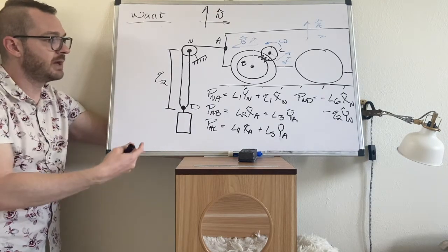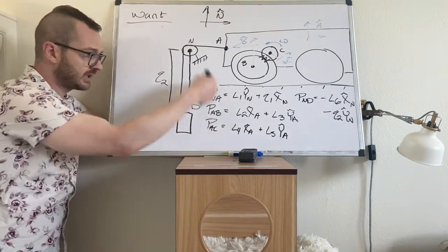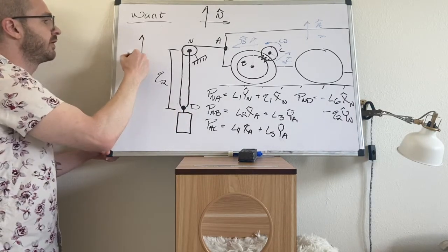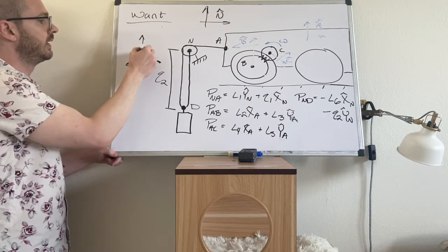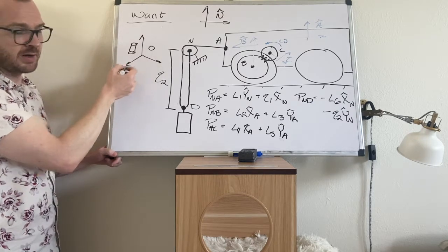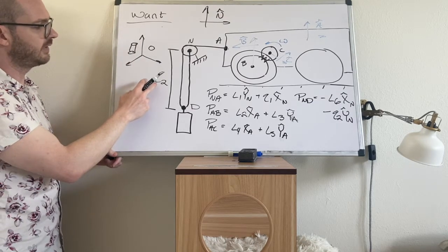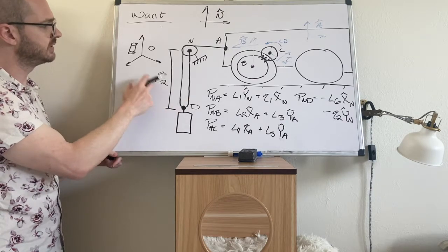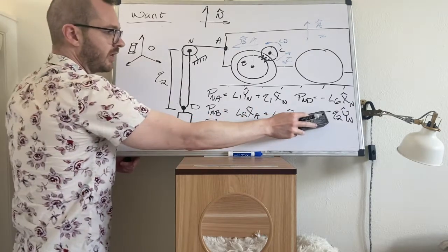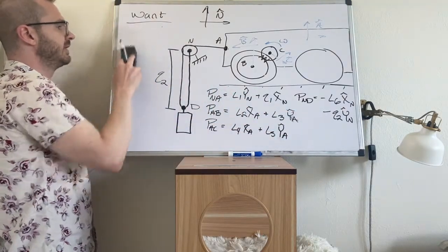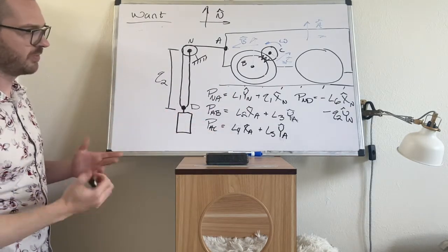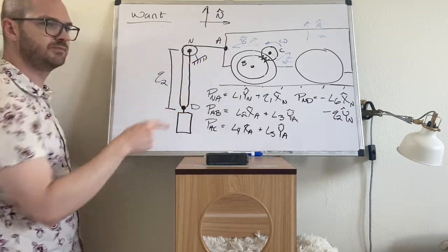And then when you go to animate it, you have to remember that it's actually below it. So if you're animating this thing in Python or in MATLAB or something, and you want to start drawing some spheres and blocks and cylinders and stuff, you have to give these bodies coordinates. And if you just take that positive number coming out of the simulation and put it into here, that means it's going to be up. So that's why I usually do all my variables as positive, because whatever numbers come out of the simulation, you literally take those numbers and put them into your animation, and you don't have to worry about signs. But just to prove that we can, let's do that.